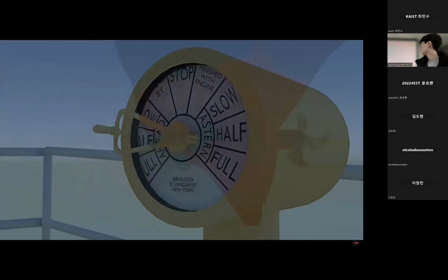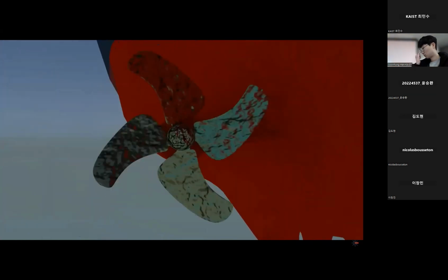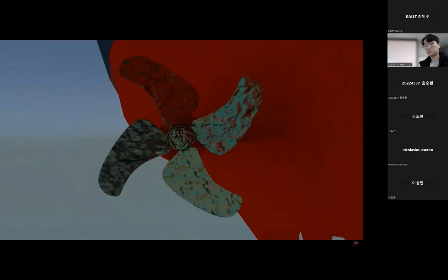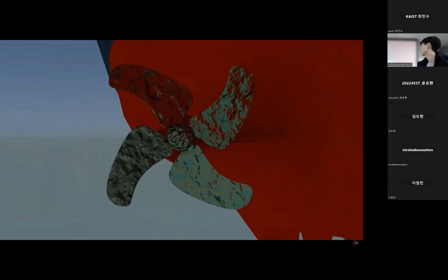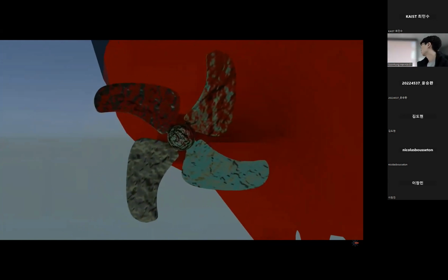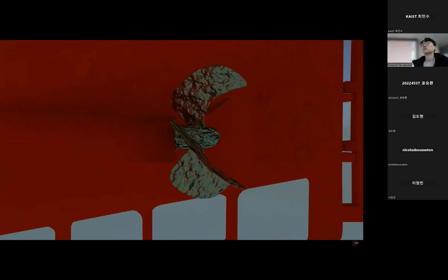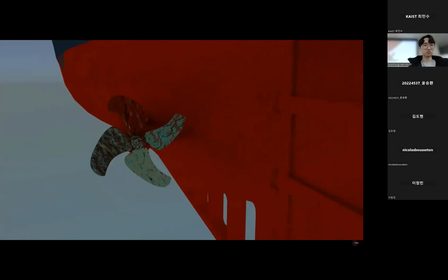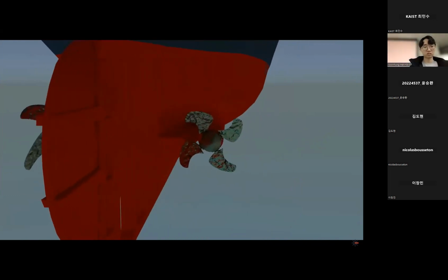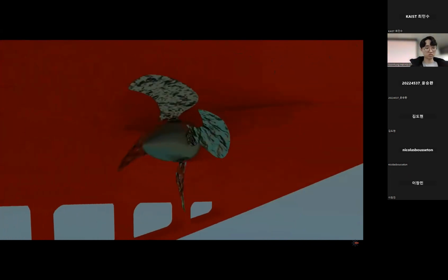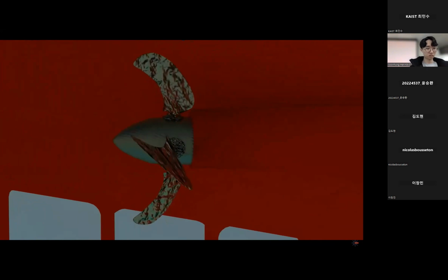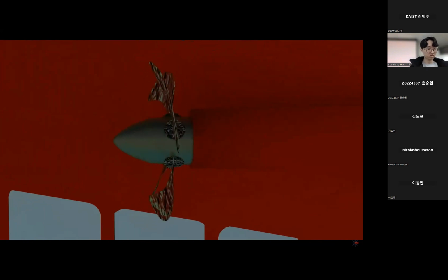To reduce the speed of a fixed propeller, you have to slow the rotation. Very easy if you've either got a gearbox or an engine that can easily vary its speed. It's a bit harder when your engine likes to run at a constant speed. A controllable pitch propeller, on the other hand, runs at a constant rotational speed. To reduce the vessel's speed, you change the angle of attack of each blade instead.